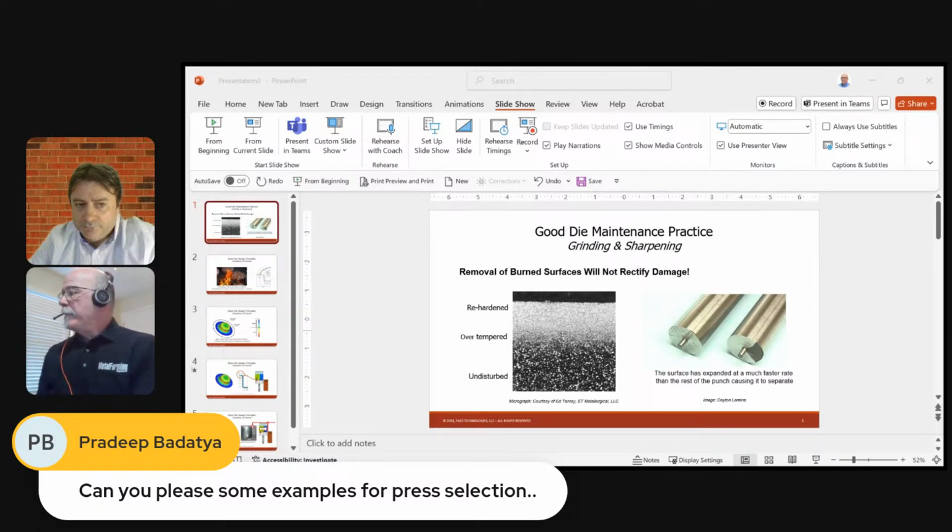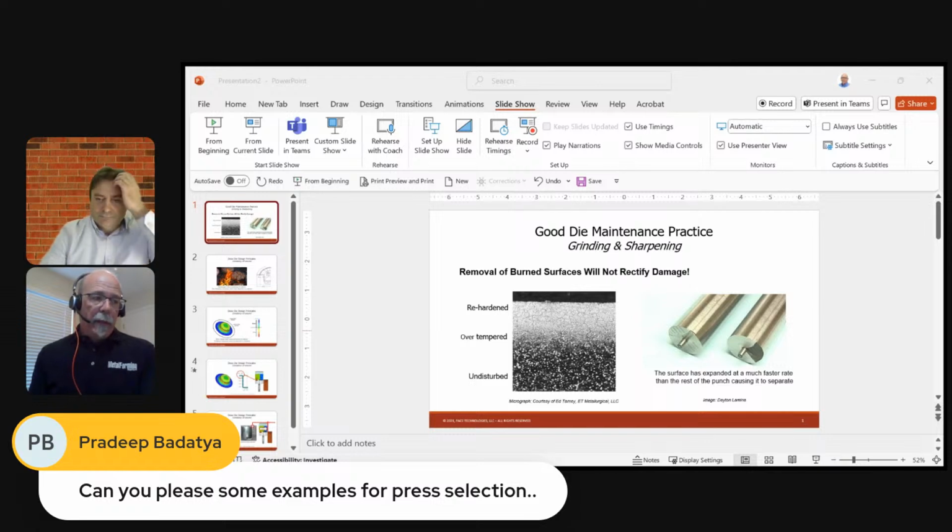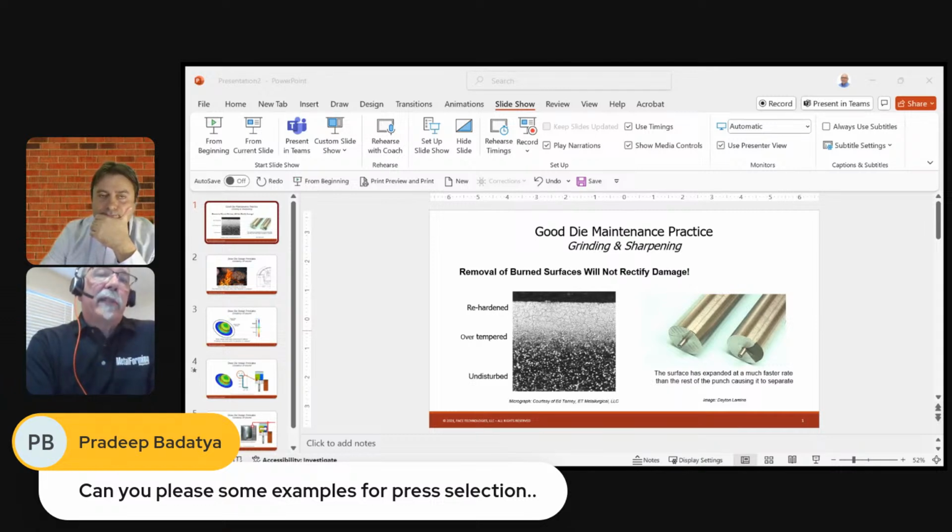So what I've seen in some high-speed stamping applications in terms of sensoring, sensors will be placed in the die to actually detect halfway through the progression. They'll have a sensor detecting, at a certain time period, that material should have progressed halfway to its stopping point. If it hasn't, then we use that sensor to stop the press, because by the time the signal gets sent and the press actually stops, they were able to stop it in those scenarios.